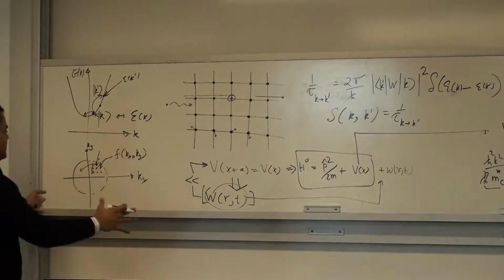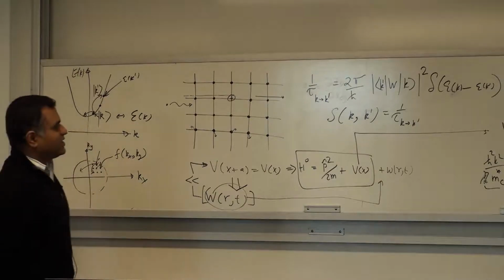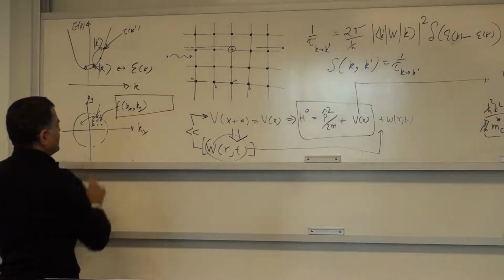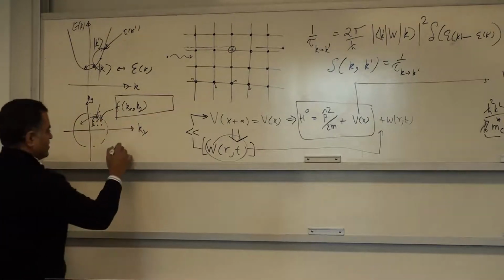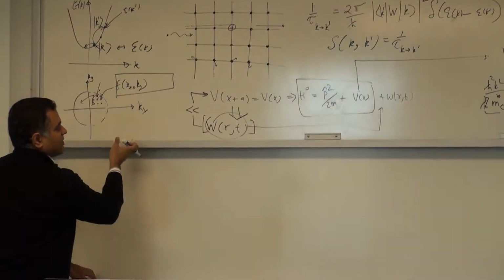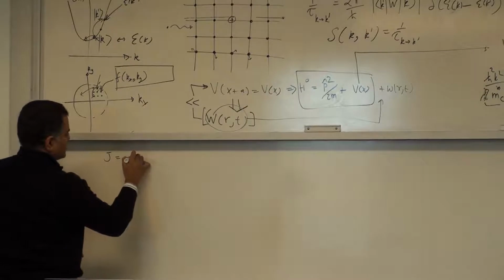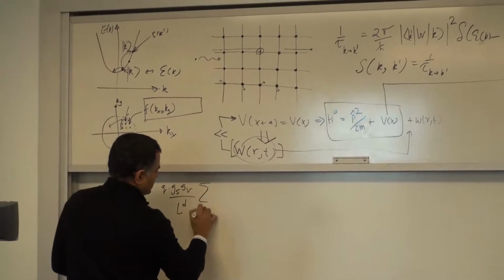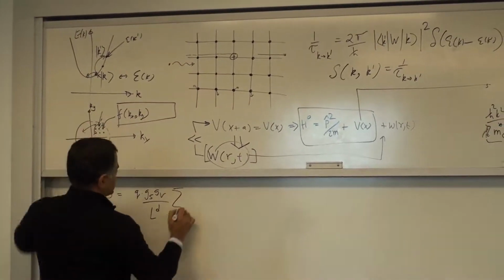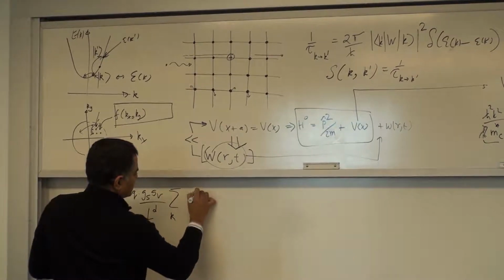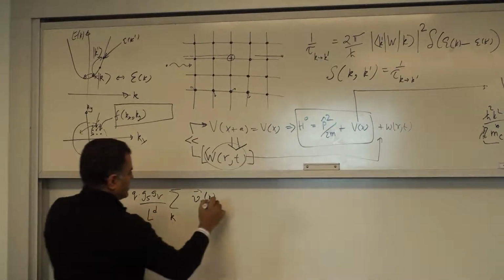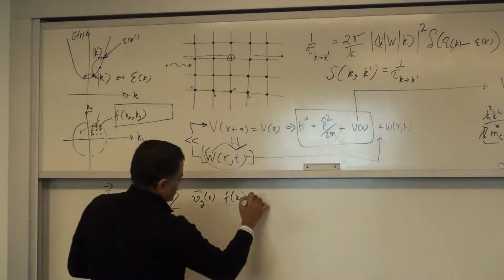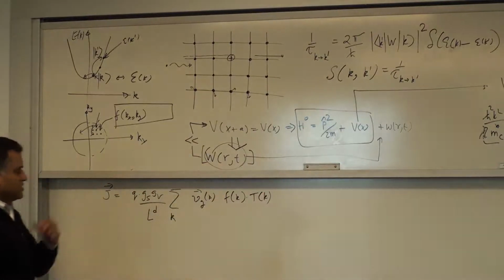And we basically are going to have to look at the full-blown distribution function now. We want to know what is f of kx, ky, because once we know that, I can go back to my full expression for the current, which is, in any dimensions, you sum over all k modes, and take your group velocity of that mode, and the current density is times the occupation function of that mode, which is what we are after, times the transmission probability if you have one.